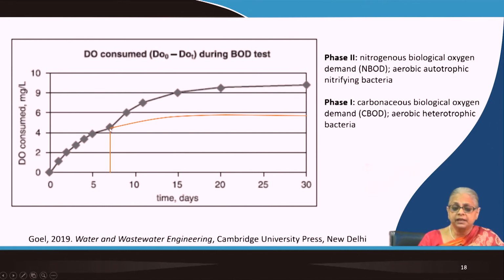Then we come to the second part of this curve, where there is an inflection. This second phase is when your carbon containing substrate is beginning to dwindle. Oxygen levels are still reasonably high, enough to keep this group of bacteria happy.